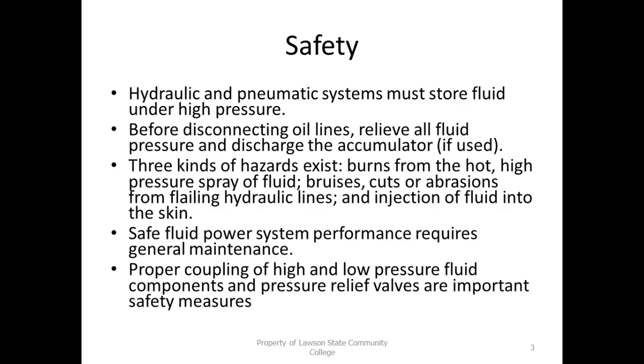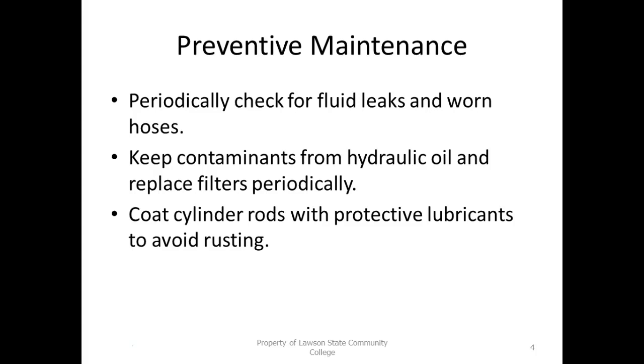Most hydraulics, we don't have a lot of problems because most of the hydraulic fluids we use are oils. And what's nice about oils is they're self-lubricating. Check for leaks and worn hoses, and keep contaminants out. And by the way, hydraulics use oils, so what happens if you have an oil leak? Now you've got slippery stuff all over the place, so a lot of times people trying to work there slip and fall too.